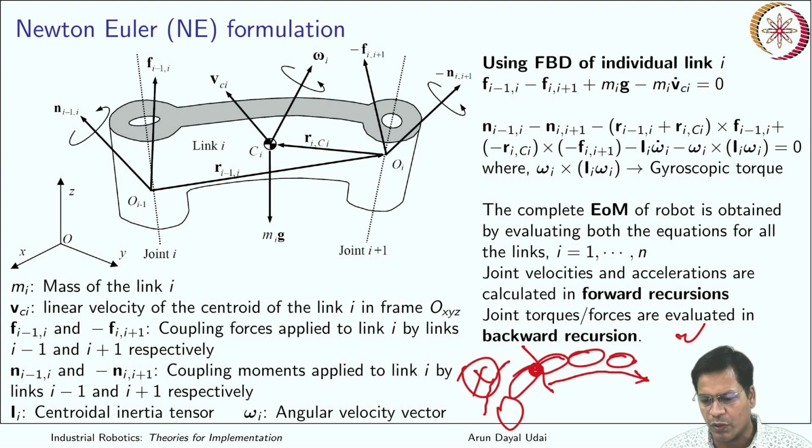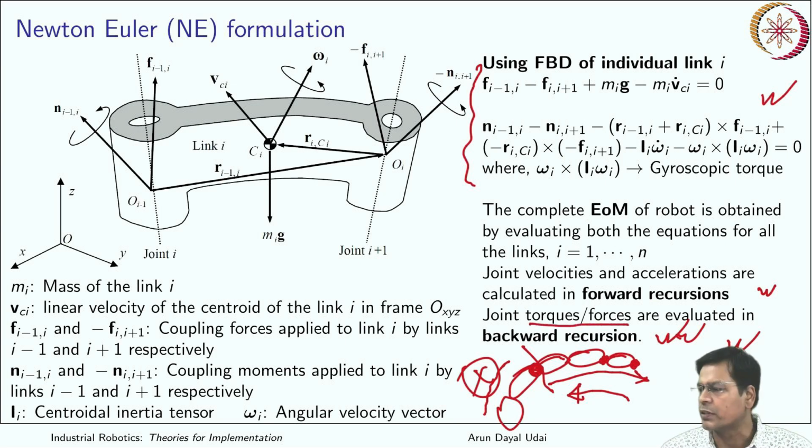So you know your constraints which are acting at the tip, then you know this, and you move like this. Okay, so that is the reason you are moving backward. So using these two pair of vector equations for all the links, you calculate the joint velocities and acceleration, as we have discussed in an earlier module also while discussing differential motions. Okay, so you use these equations, and you can do backward recursion to calculate the moments. So moments are projected further along the joints to obtain the torques at the joints.